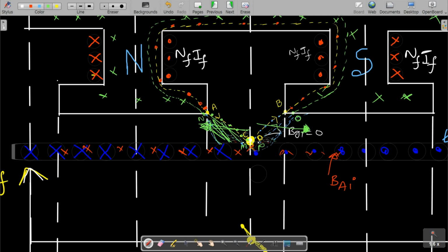So if these flux line lengths are decreasing, that means those are nothing but the gap lengths. Whatever I have said, that x and y, those gap lengths are decreasing. So if the gap lengths are decreasing, then flux density must increase because B is inversely proportional to the gap length. So from this side, the gap lengths are decreasing, that means B will increase. And on this side the gap lengths are decreasing, so B will increase.